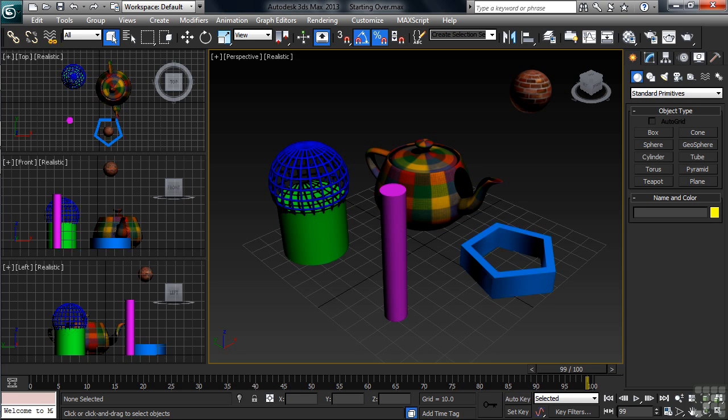Using New, you keep your viewport layout, your snaps remain as they've been set, even whatever skins were built in the material editor hold over from the last project that you had on the screen. You could even keep your objects if needed, and have a few choices as to what to do with any animation that's been keyframed into the scene, or any linking between objects that might have been set up. Every bit of that, if needed or wanted, can be carried over to a new scene.